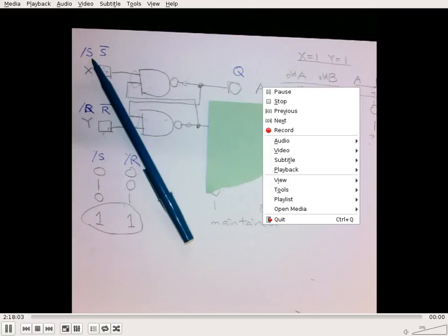Okay. Yeah, this type of thing is also called active low when it comes to electrical engineering. So when you look at the slash signal, sometimes we call it active low, because a low voltage means, yes, this is what we want. And there are many signals on a computer chip that are active low.